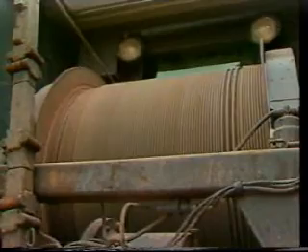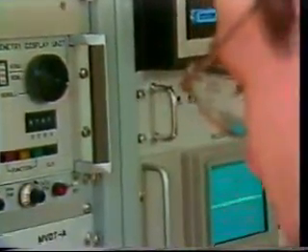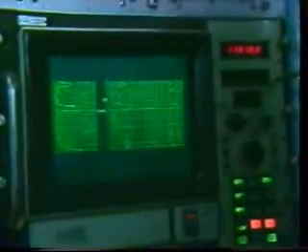At this point, we need a word about depth determination. This process involves more than simply lowering the tools to total depth and reading the depth on the meter. Service companies use certain procedures to ensure that the depth reading is as accurate as possible. Check with your service company for an explanation of their particular procedures. Now, as the string of the logging tools is lowered into the hole, the logging engineer again tests tool responses. Often, benchmark lithologies like salt or anhydrite are used to confirm that accurate readings are being obtained.